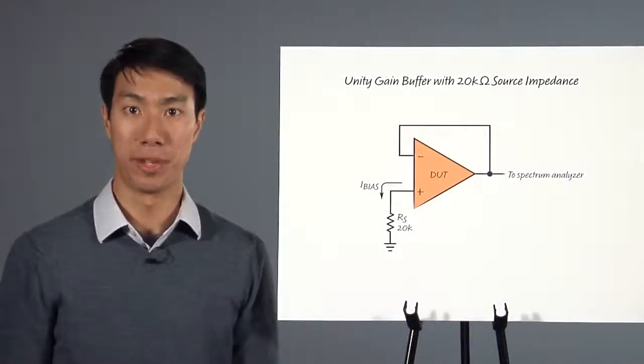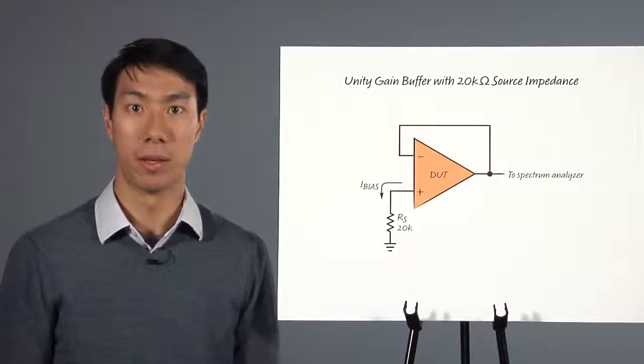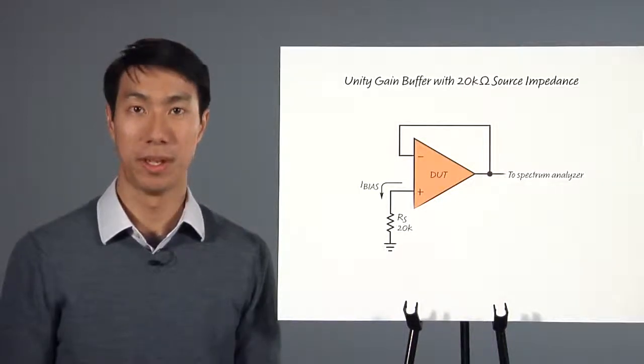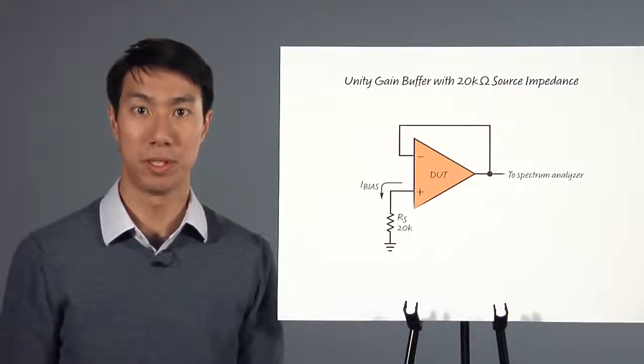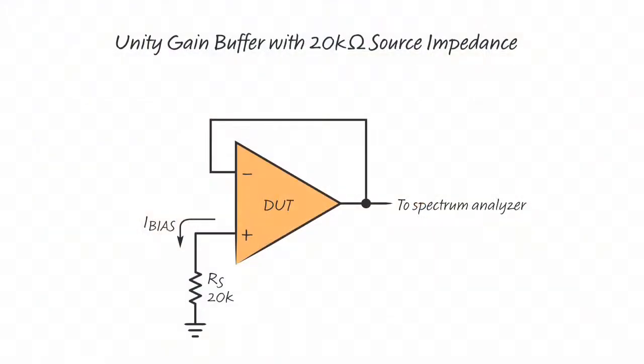Another artifact that you may encounter is clock feed-through. Unlike ripple, which is a type of voltage noise, clock feed-through is a type of current noise. If you are working with large source impedances or a transimpedance amplifier, pay close attention. Zero-drift circuit techniques require a set of switches at the amplifier's inputs. During each switching event, a small pulse of current is injected into the external circuit and will interact with any source, gain setting, or feedback impedances that the amplifier sees. The result will be an unwanted transient voltage at the amplifier's input.